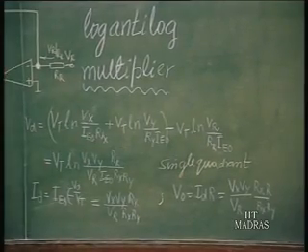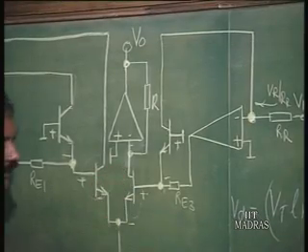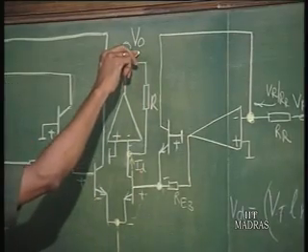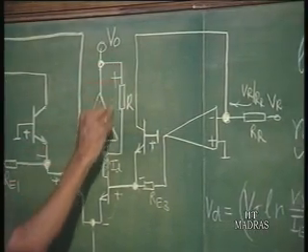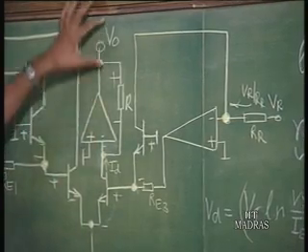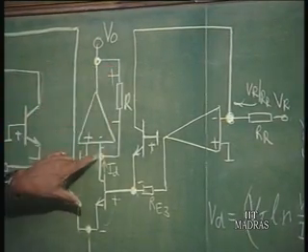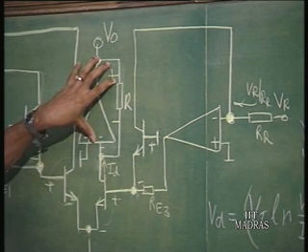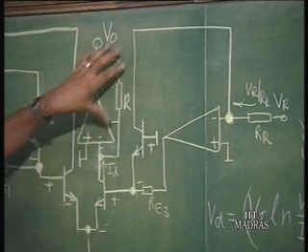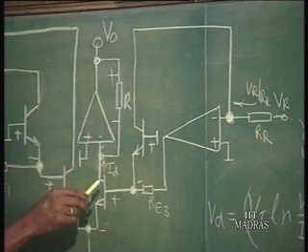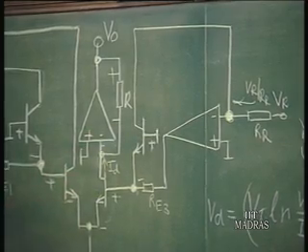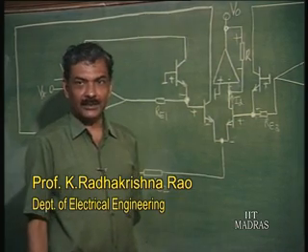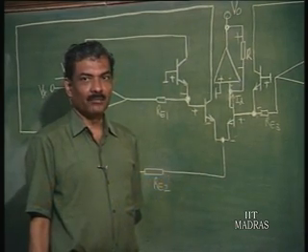So, this generates then a current, which is I diode, which is going to pass through a resistance R, and therefore that will be developing a voltage like this. So, V naught is going to be nothing but ID into R, this is at 0 volts. So, this amplifier converts that current into a voltage ID into R, and as you can see here, if you have 4 op amps and 2 pairs of transistors matched, you yourself can build a very accurate log-antilog multiplier.